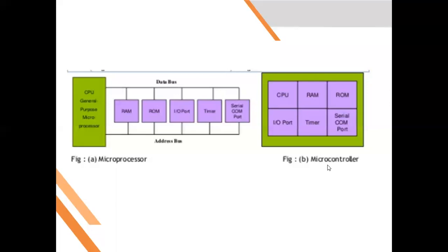Okay, now look towards the controller. It is a single chip. On that single chip you are having CPU, that is your microprocessor. Again you are having necessary devices, which are these: IO devices, RAM, ROM and timer counter. Okay, and serial port. Because it is a compact structure which gives you all the facility on this single chip. Once you buy this single chip, you will get all the necessary devices which are used to run some specific or basic operations.